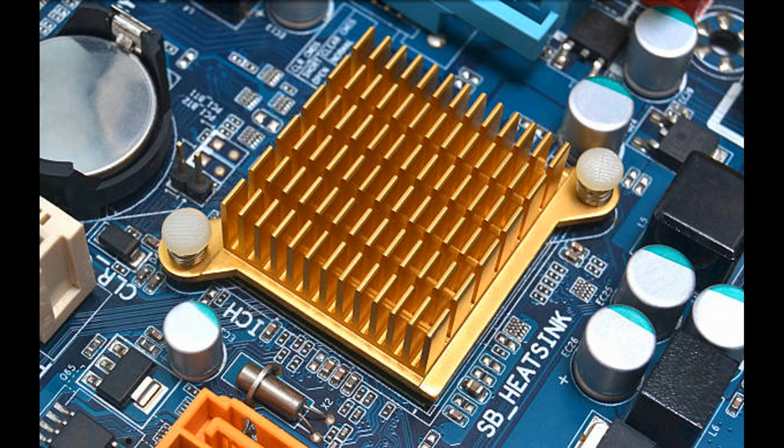Functionally, a thermoelectric heat sink works based on the Peltier effect, which occurs when an electric current passes through two different types of semiconductors joined together. When an electric current flows through the thermoelectric module, heat is absorbed at one junction, the cold side, and released at the other junction, the hot side. By reversing the direction of the electric current, the heat transfer process can be reversed, allowing the thermoelectric heatsink to both cool and heat as needed.